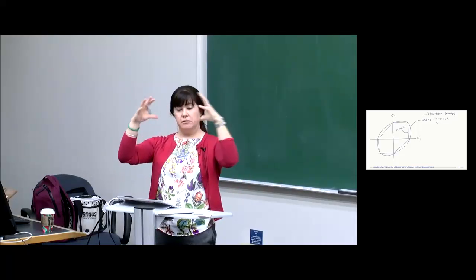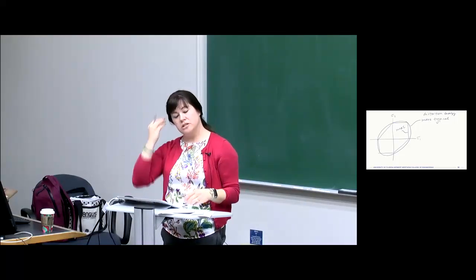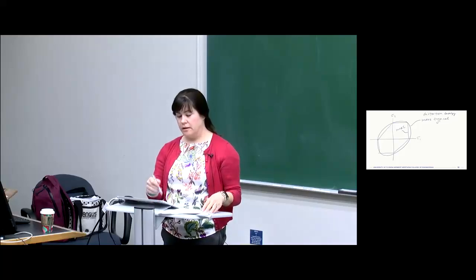Okay? And so this is more typical of data. And this is the distortion energy theory. And this one is the max shear stress, the one on the inside. And so you can see that the failure envelope for distortion energy is a little bit bigger. So this confirms the idea that the shear stress theory is slightly more conservative.